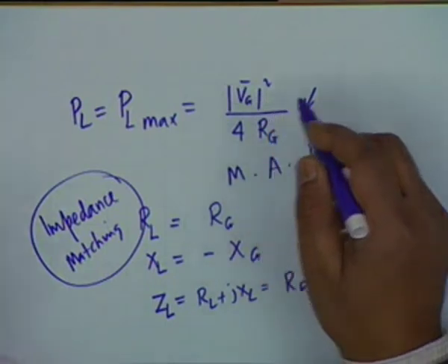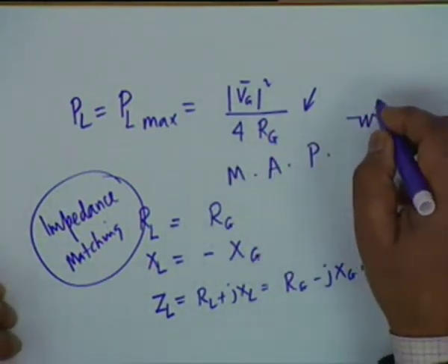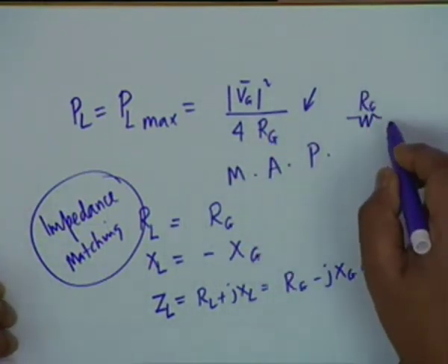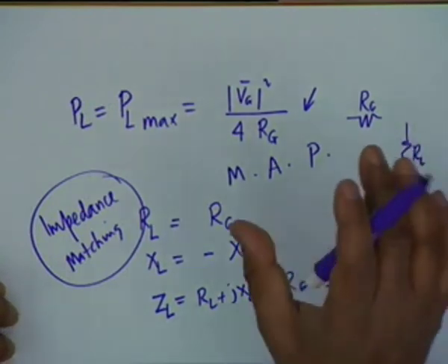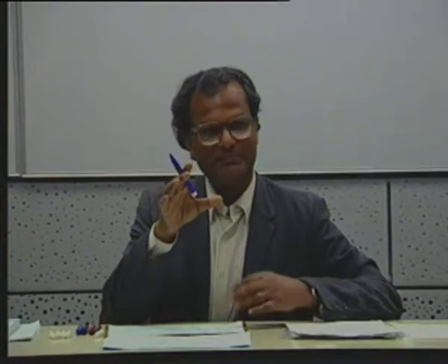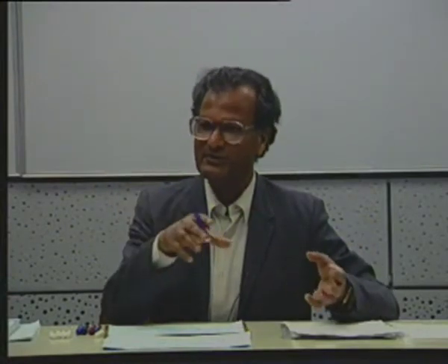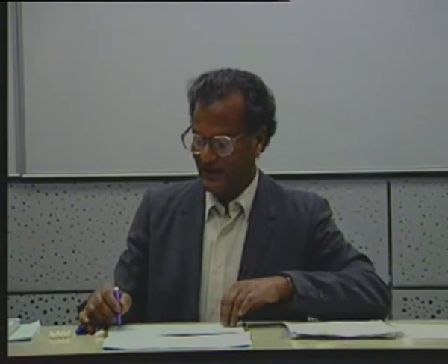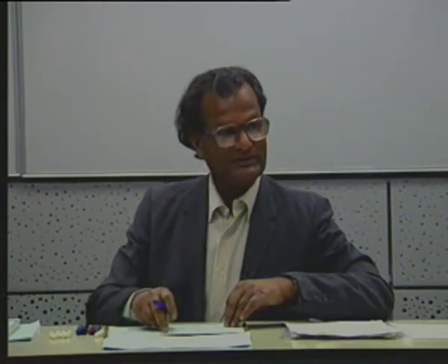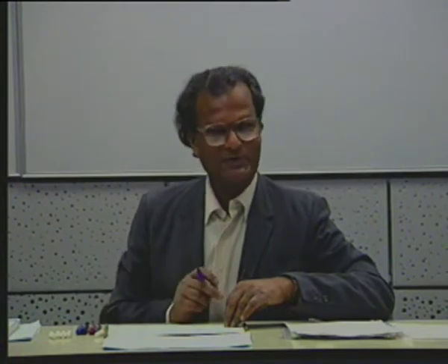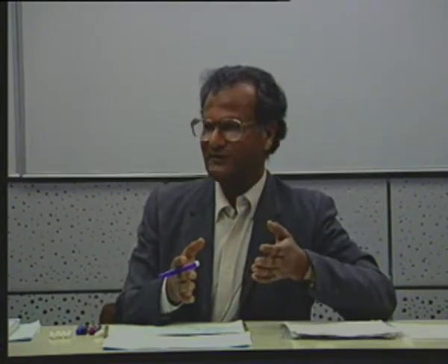Isn't that right? You see, the source delivers through a resistance to a load RL, and when the load and source are matched, that is, one is the complex conjugate of the other, RL absorbs this amount of power. This amount of power must then be absorbed by Rg also, so half of the power is wasted in the source.